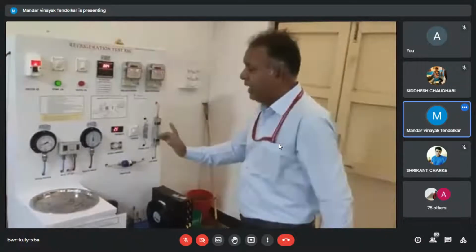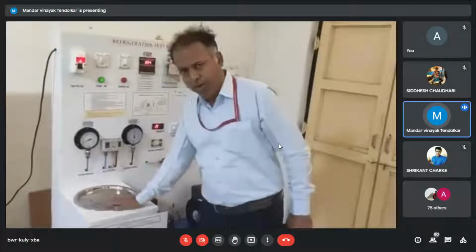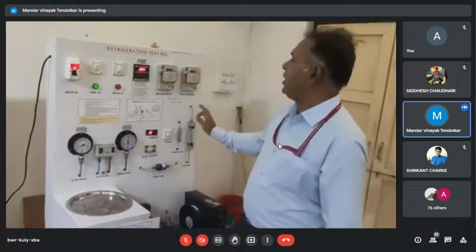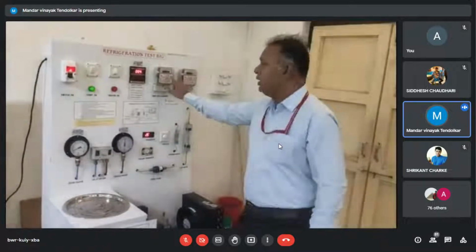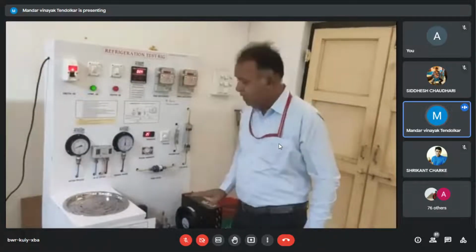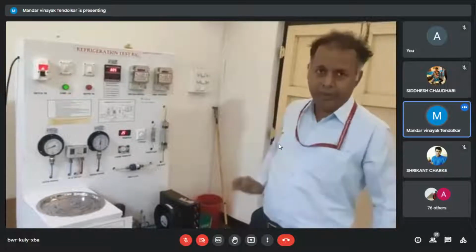Okay, so first thing is you can find the refrigerating effect experimentally by noting down the temperatures of the water, m Cp delta T upon time, and one can find the power consumed by the compressor by noting down the readings of the meter which is installed in the setup. Okay, so this is how one finds what is called the experimental COP.